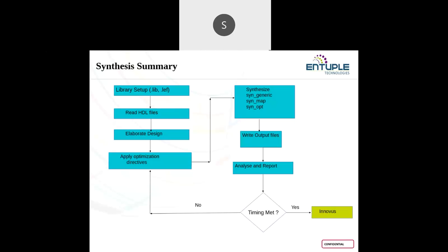Any queries? Ma'am, one more question. From the gate count report, is it possible to find the physical area? No. See, gate count just gives you how many cells, how many instances are used in your design. That count information you can get. But logical information, as I have already told, for each and every cell,